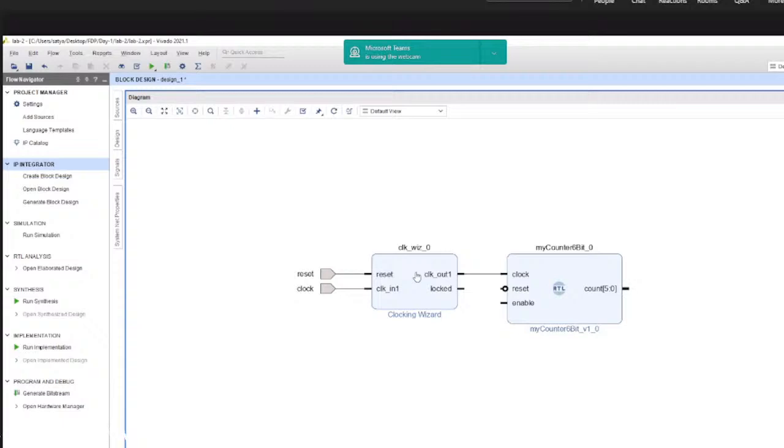Because the PLL goes into a locking mechanism phase in order to perfectly establish the clock signal with the desired frequency. Once the clock signal has been established after the locking mechanism, at that time you will be getting the actual clock signal. So whenever the PLL is locked, the locked output will be active high.